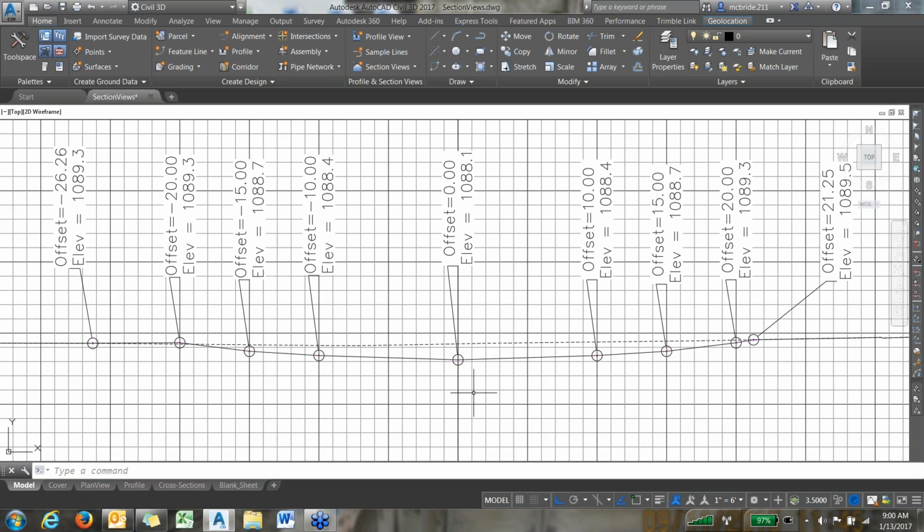Then when you get to the end, you can have the waterway built, and 5-10 years down the road, whenever it's got to be reviewed, people can go out there and they can redline on the plans, and they can say, okay, in a 5-year review, this elevation is now 1088.2. You can redline that right on there, or if the plans change when you're building it, you can redline that on there as well. It just gives you a nice place to write that in.